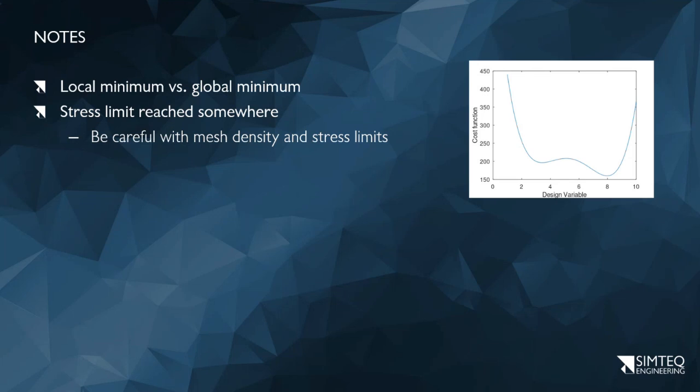So you run an analysis and you're used to running an analysis where, let's say the stress limit is 200, I get 180, I'm happy, I sign off the design. But in this case, now my answer is 200 exactly. Now what? And that means my mesh has to be fine enough to capture a really accurate result. My stress limit is perfect, my material, everything. So we have to then, if we want to run an optimization for that as a limit, either reduce that limit a little bit to say 180 because I feel safer there, that gives me margin for inaccuracies in my mesh, or we have to mesh super fine to try and improve that result.